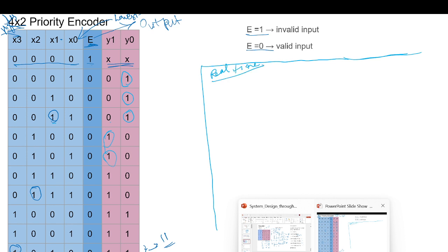You know about flash ADCs? If I have, say, any input voltage, say 0.7 volt, it will be converted to levels. Say I have an n bit ADC, say 2 bits, I will have 4 levels.